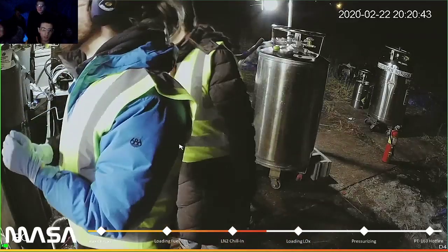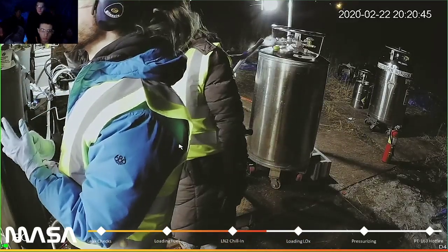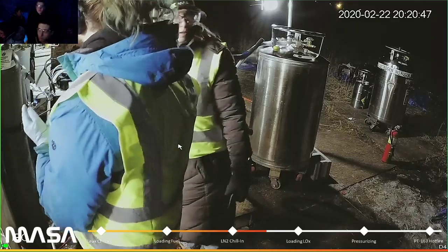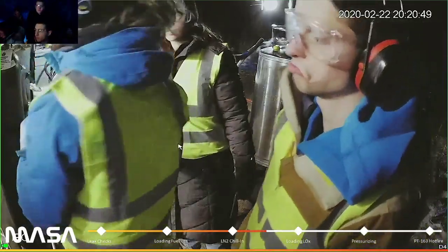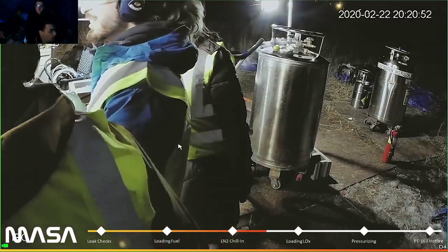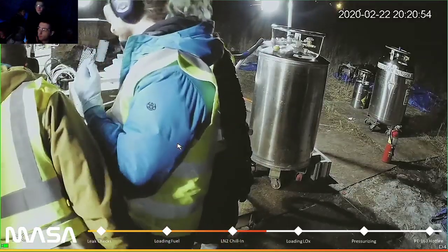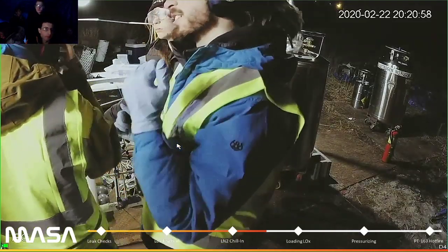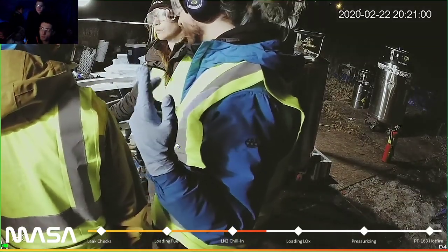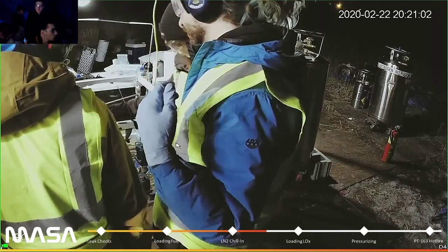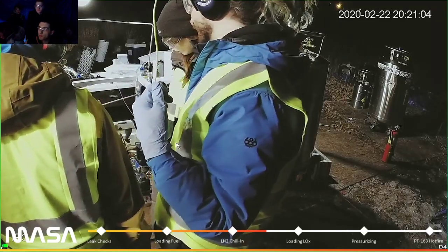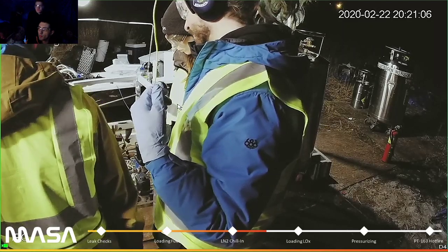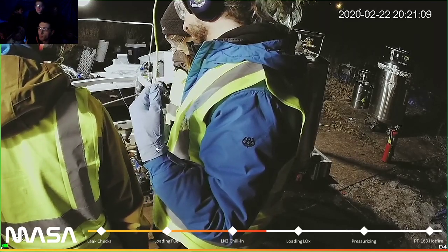Basically, we're not worried about fuel pooling up, because we have an extremely powerful igniter, and that turns on before any propellant is flowed in. So even if we have just liquid fuel and no oxidizer, the fuel is instantly burned up and nothing has a chance to pool. So there's no issues with horizontal testing. We've been doing horizontal testing for several years in various configurations.